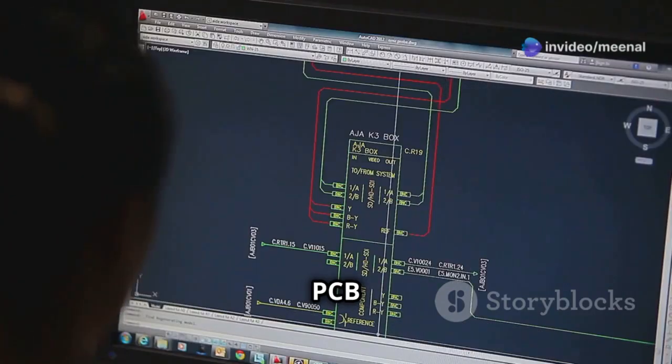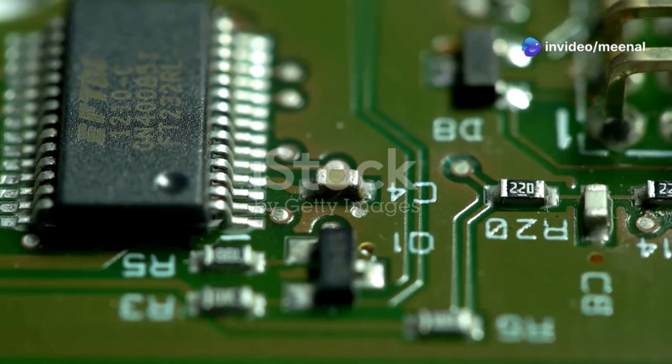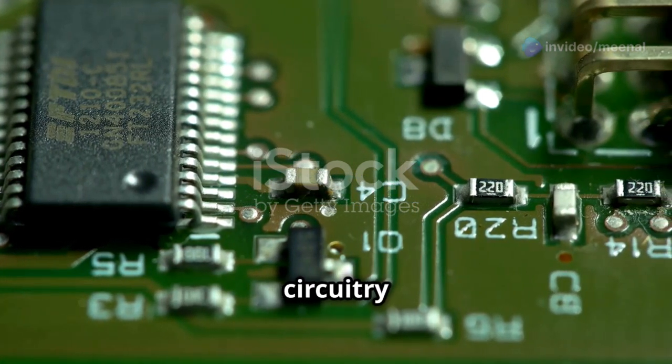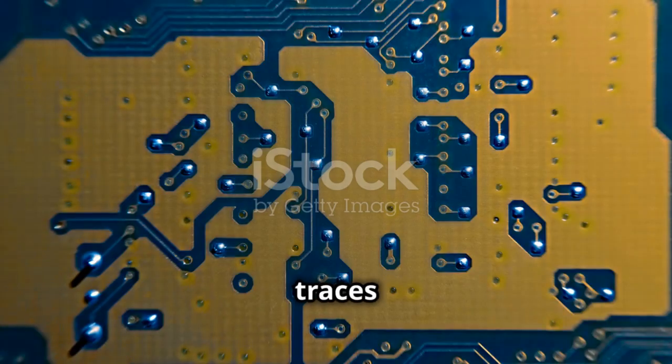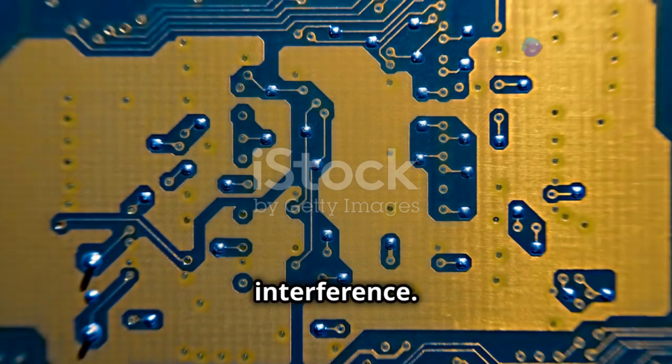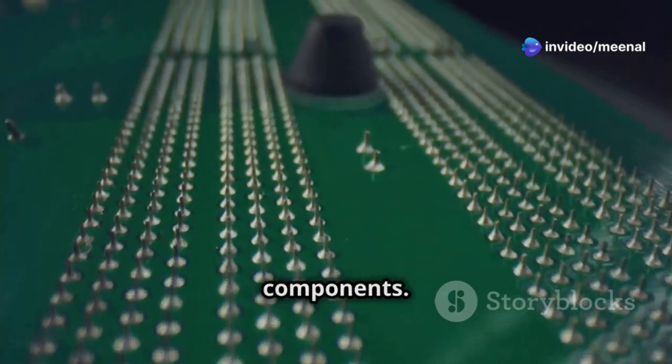Now let's move on to PCB design for reset circuitry. PCB design for reset circuitry is about ensuring the reset signal remains clean and strong. Keep signal traces short and direct to minimize noise and interference. Avoid routing reset signal traces near high-speed signals or noisy components.